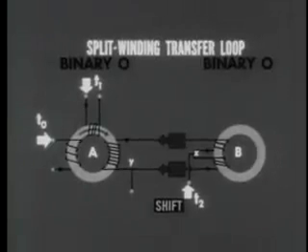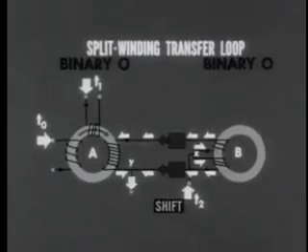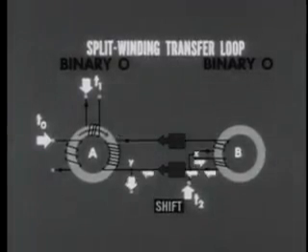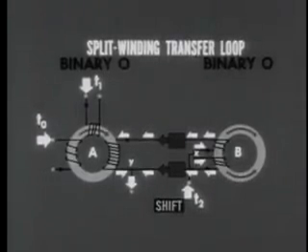The result is no change in either core. Core A remains at 0 because the upper branch current is applied to its winding as a dot pulse. The upper and lower branch currents are equal, and therefore core B also remains at 0, because equal currents there produce opposing but equal magnetic fluxes, which cancel out.